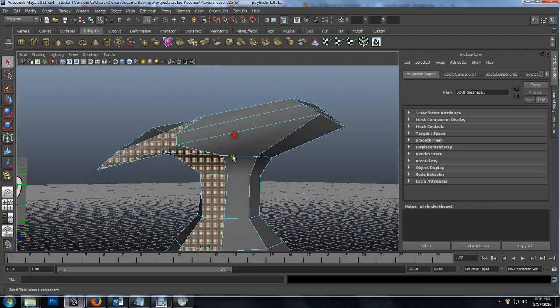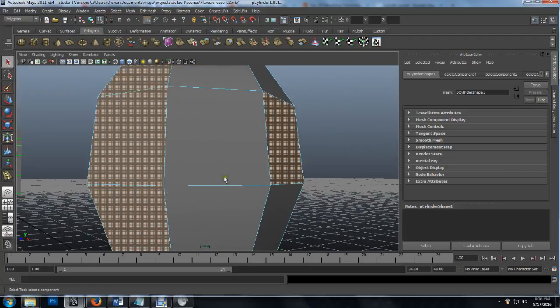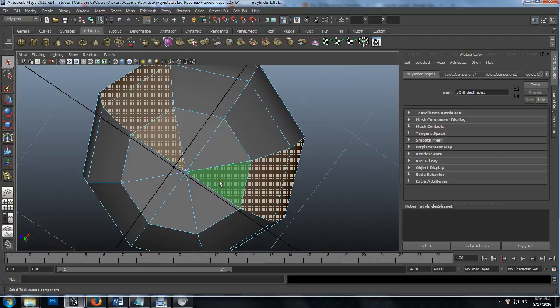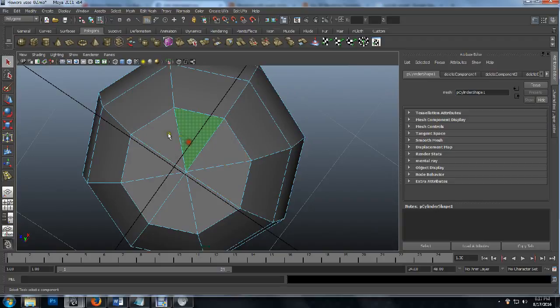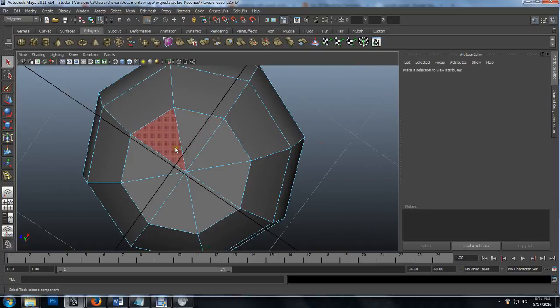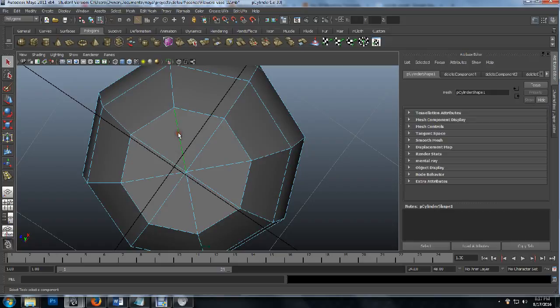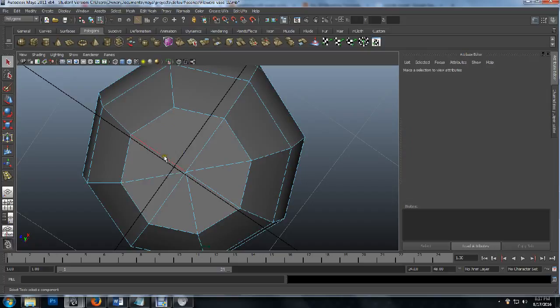And if we were to rotate all the way down to the bottom, see how they stop on these triangles? So, same thing down at the bottom. I'm going to cut these off. So I'm going to go and grab my edge tool. So that's F10 to get in edges. And this one I should be able to cut and make a quad. 1, 2, 3, 4. That's 1. And then this one, 1, 2, 3, 4.